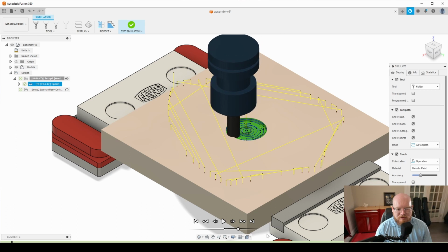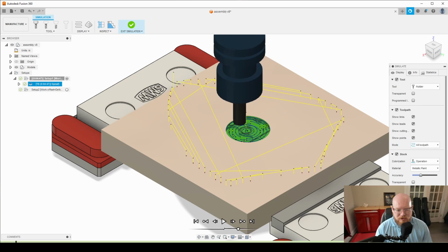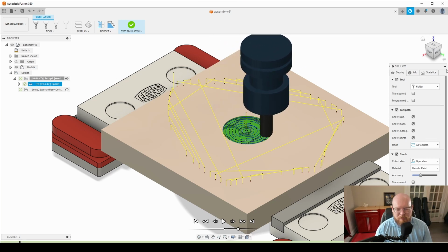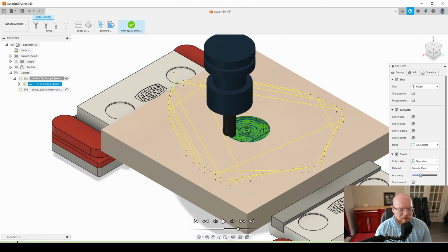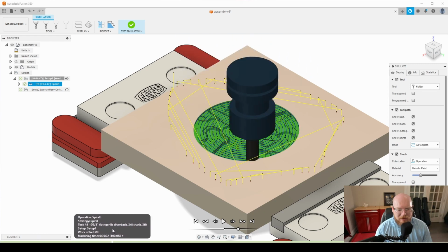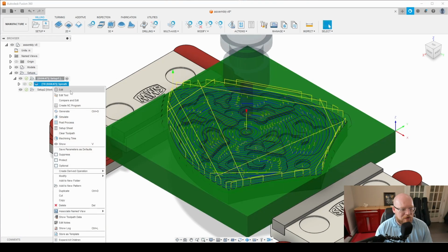I want that center pocket to be one 3D pocketing toolpath where I use a 1/8 inch end mill, and I want the top surface finish to be as smooth as possible. So again, go ahead and drag just a little further here. That is why I want to use the patch, to prevent the tool from going into my part and to get a nice smooth surface finish where we have a continuous machine motion without all of the retracts in Z. So I'm going to exit,